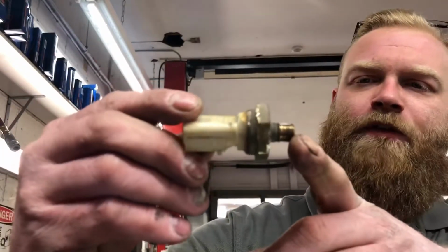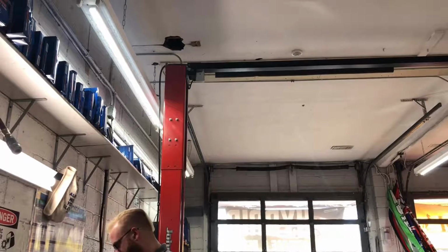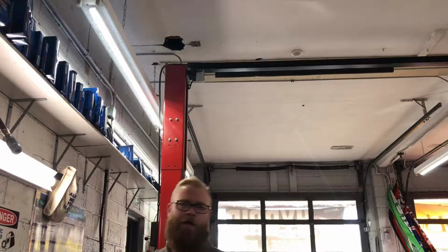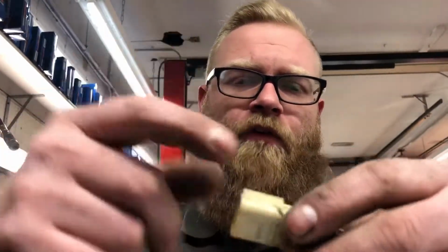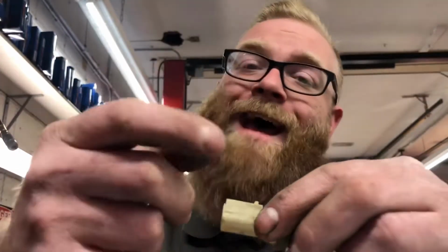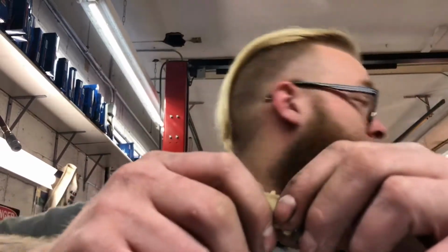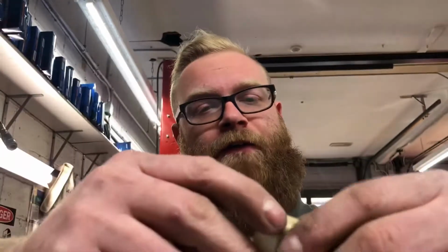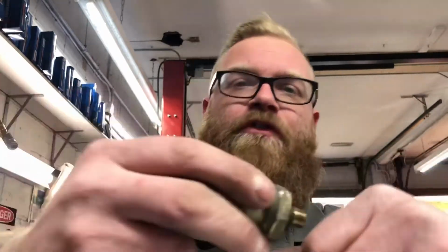So you just get in there with a socket. I'll tell you what size socket it was. It's a 1-1/16" socket you get in there with. Pull your old sensor out. This is a Chrysler connector here, so you do have that red tab. You got to push the red tab through and then go ahead and unplug the connector. Once that's done, you can go ahead and unthread this, take it out, and thread your new one back in. It's a really quick job.